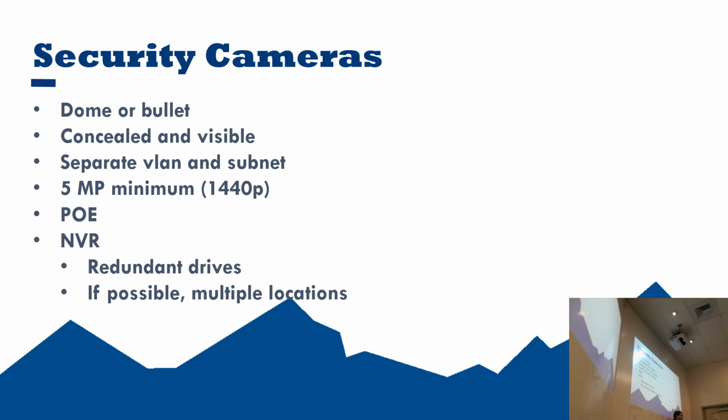This is a personal suggestion: I suggest a minimum of 5 megapixels, which is going to be 1440p resolution. In my opinion, everything I've ever seen or read suggests that 1080p is not really good enough to read things like license plates and facial details. There's just a huge difference between a 3 megapixel and a 5 megapixel camera. Of course, 4K is going to be 8 megapixels. I think that's pretty self-explanatory.